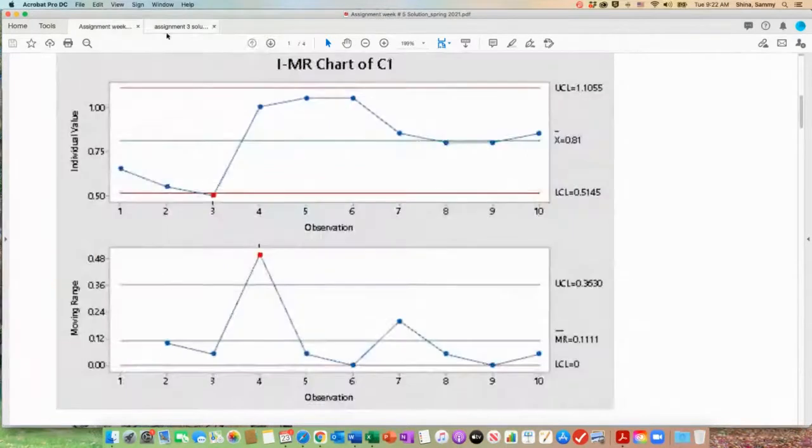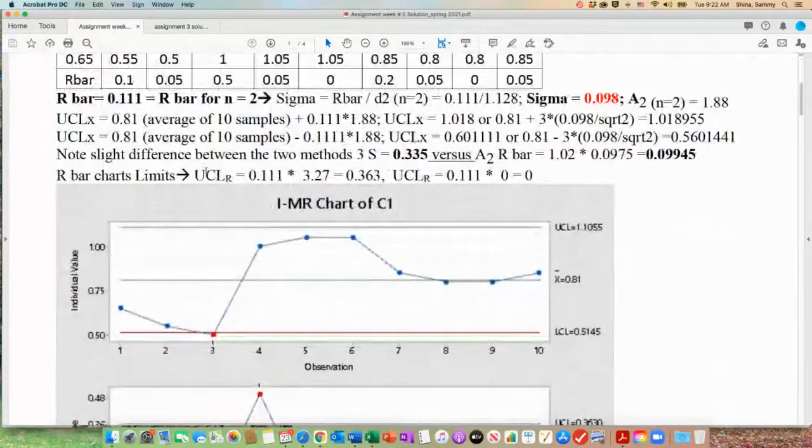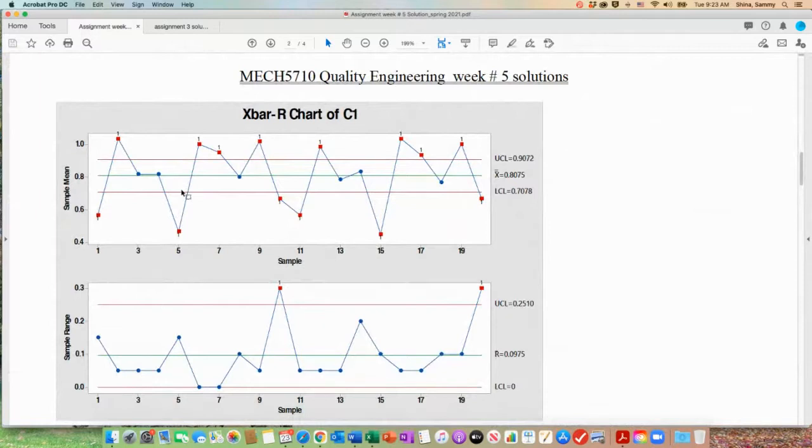Also this afternoon, we're going to give you an example of how Minitab makes control charts. There are two kinds of control charts. One is a regular X bar R control chart, which is a chart of sample averages. You take a sample, you design the control chart limits, and the limits sit at plus or minus 3 sigma.